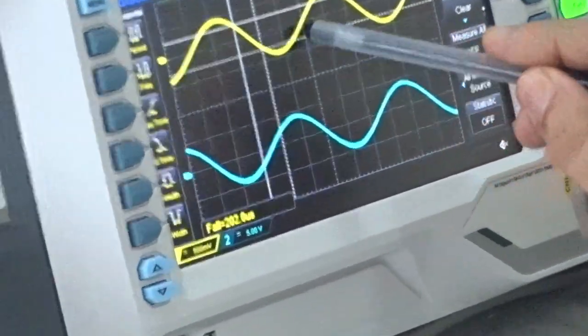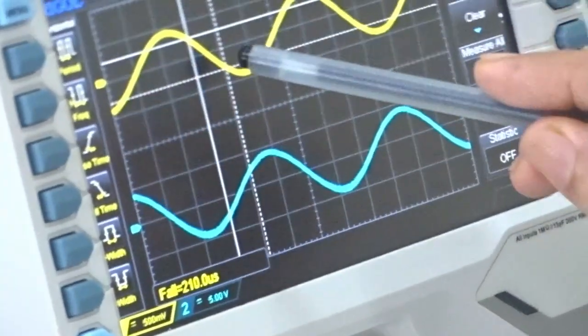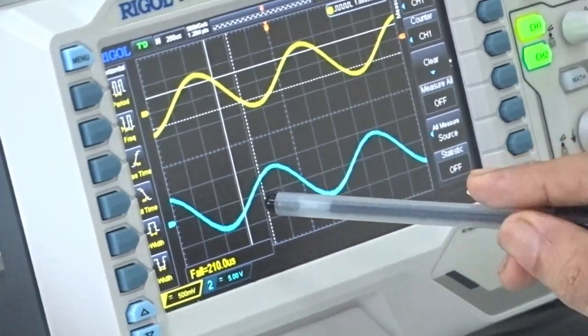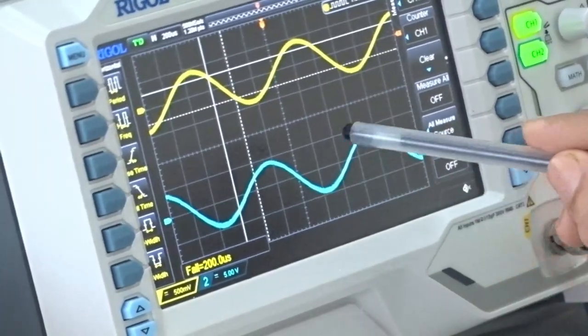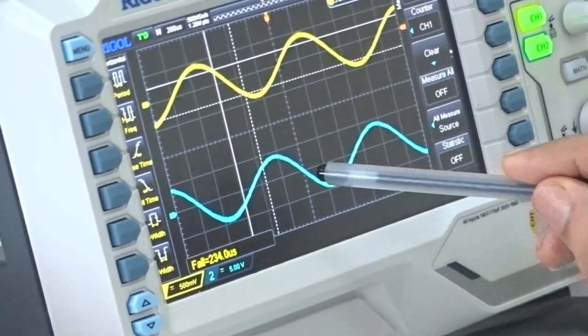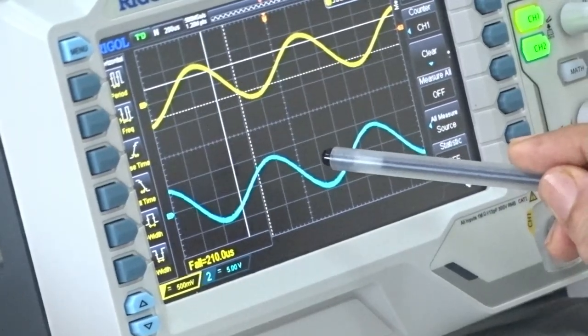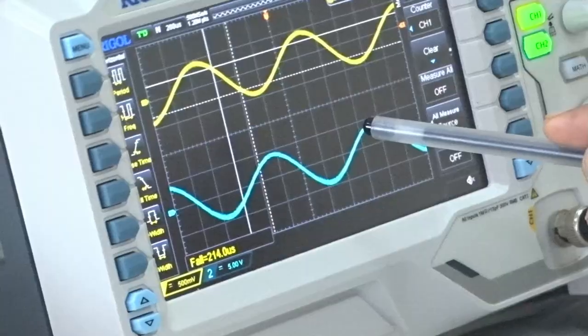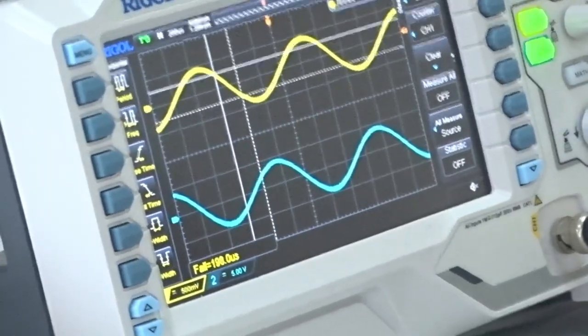So this is the input signal. We applied an input voltage of 1 volt. For this input voltage, the output is the inverted version of the input, and as I told, it is 180 degrees out of phase with the input signal. So for the inverting amplifier, a phase shift of 180 degrees is available at the output side.